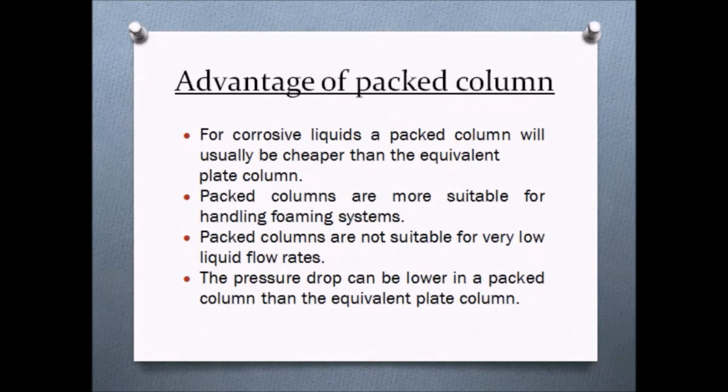There are many advantages of a packed column. One of them is that for corrosive liquids, a packed column will usually be cheaper than the equivalent plate column. Packed columns are more suitable for handling foaming systems. Packed columns are not suitable for very low liquid flow rates. The pressure drop can be lower in a packed column than the equivalent plate column.